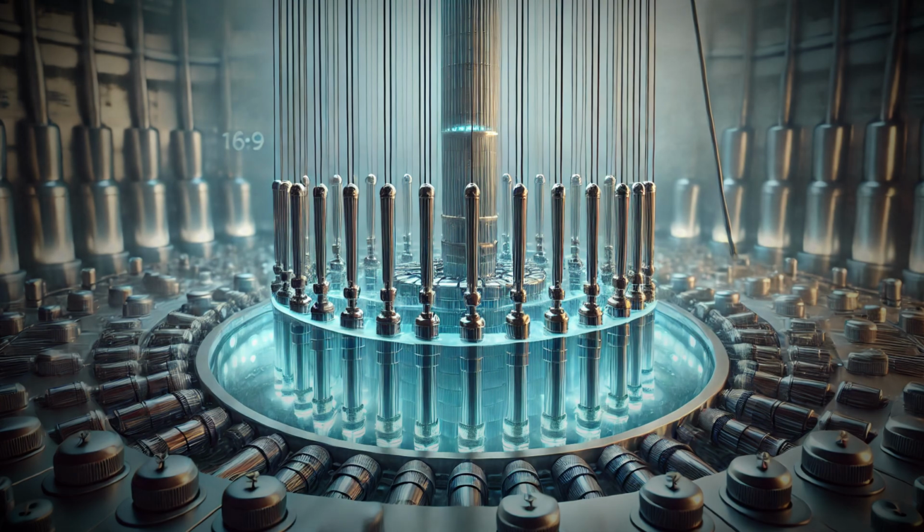Control rods and neutron moderation are essential aspects of a nuclear power plant, because without them, the chain reaction inside the reactor core would be unstable and impossible to manage. To understand their role, it is important to recall that nuclear fission occurs when a uranium-235 nucleus absorbs a neutron and splits, releasing both energy and additional neutrons. These new neutrons fly out at very high speeds, and if left unmoderated, they would be too energetic to efficiently cause further fission in other uranium nuclei.